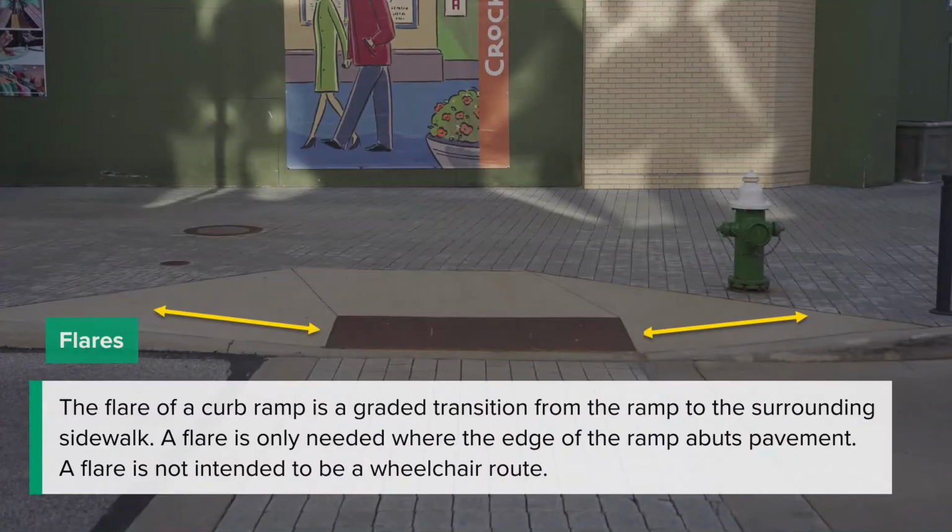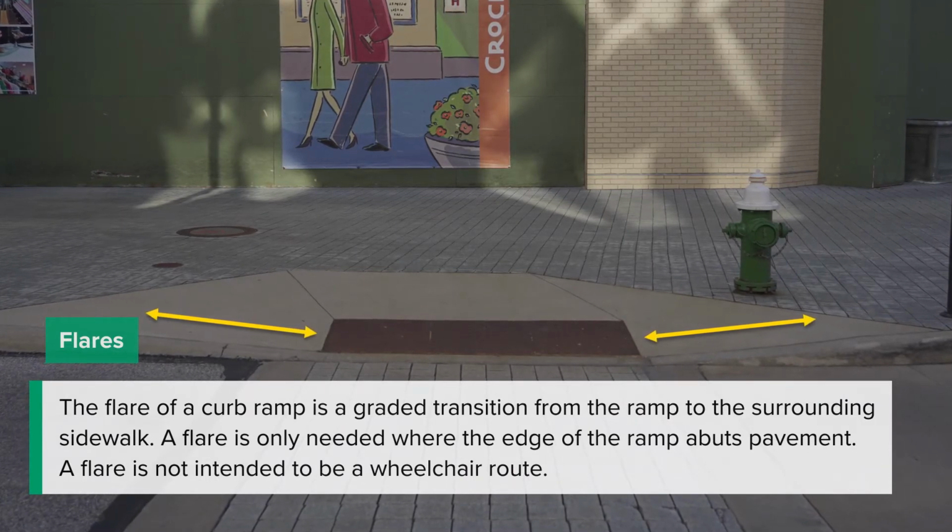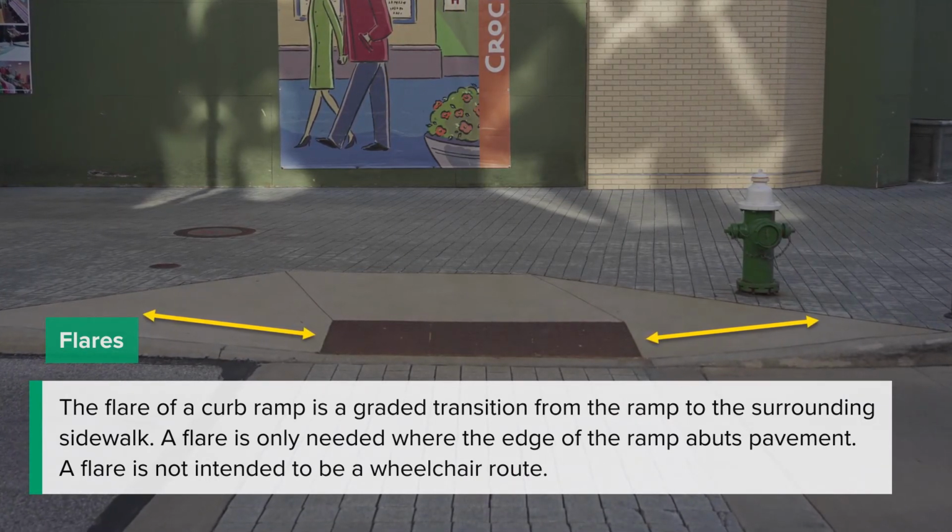The flare of a curb ramp is a graded transition from the ramp to the surrounding sidewalk. A flare is only needed where the edge of the ramp abuts pavement. A flare is not intended to be a wheelchair route.